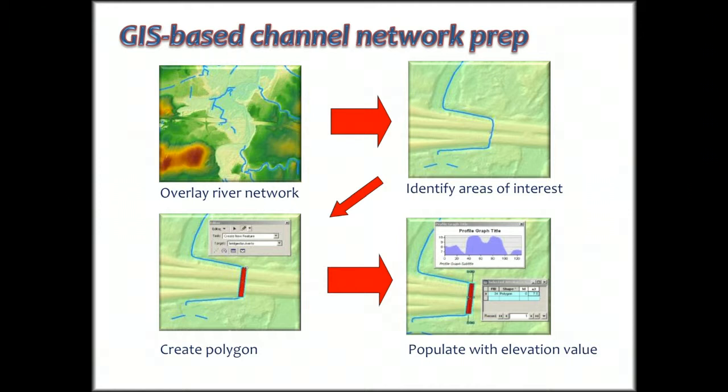And so what that means usually is that we'll start off with some idea of what the river network looks like. Sometimes we can take aerial imagery or high-resolution satellite imagery, transpose it onto our LiDAR DEM, and we'll manually see where the streams are, and we'll identify if there are any flow obstructions, just visually identify them, and then apply some kind of burning in to the DEM so that we can remove that barrier from flow so that the other automated watershed tools will work.